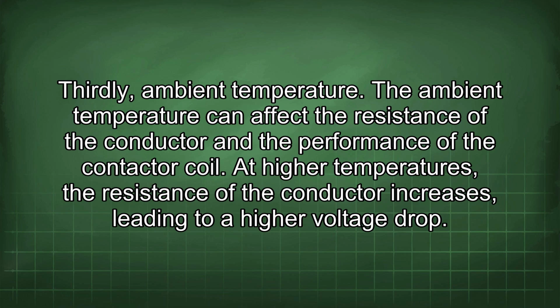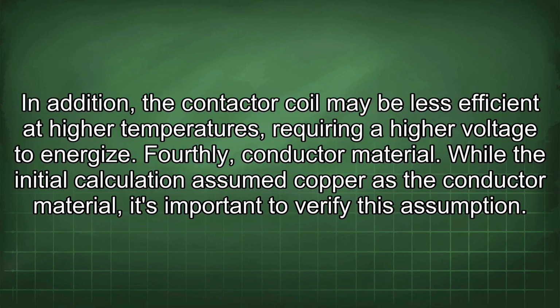Thirdly, ambient temperature. The ambient temperature can affect the resistance of the conductor and the performance of the contactor coil. At higher temperatures, the resistance of the conductor increases, leading to a higher voltage drop. In addition, the contactor coil may be less efficient at higher temperatures, requiring a higher voltage to energize.